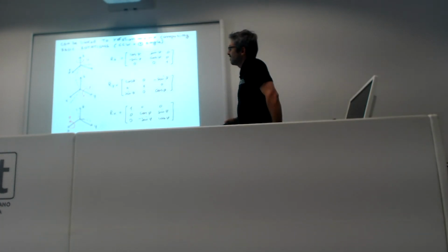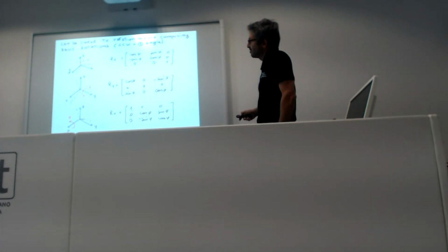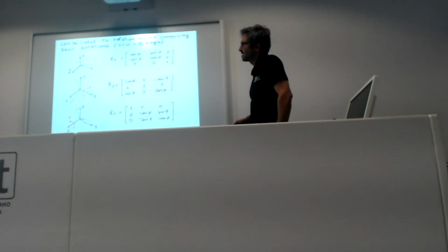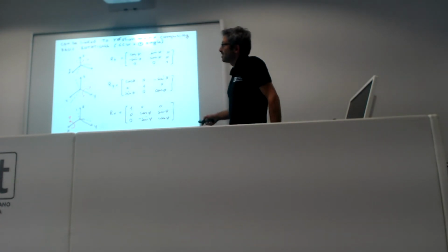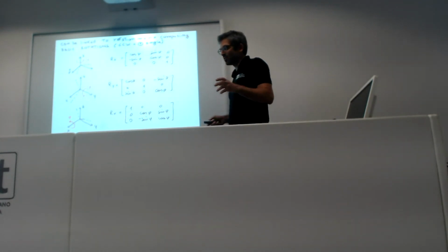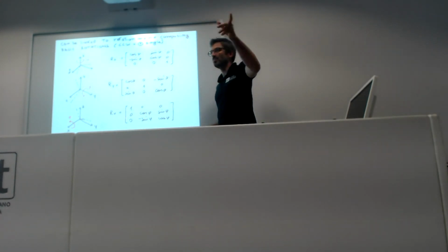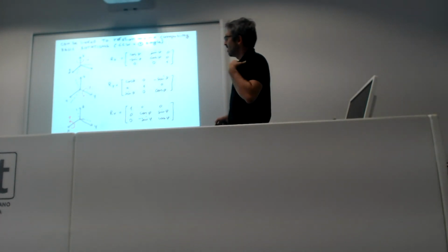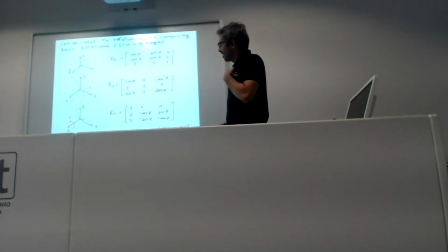And then finally we have the elementary rotation matrix around the x-axis represented by phi, that is the roll angle. Then we compose them, and we get the rotation matrix that represents the orientation of the base frame, for example, in the inertial frame.